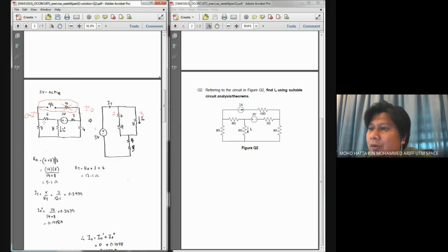Later on, after I pass the 6 ohm resistor, I also have 2 branches. However, the second branch is considered negligible because of this open circuit. Then I only consider the branch on the left hand side, which consists of an 8 ohm resistor. That's why after I'm done with the 6 ohm resistor, I connect my wire into this 8 ohm resistor.